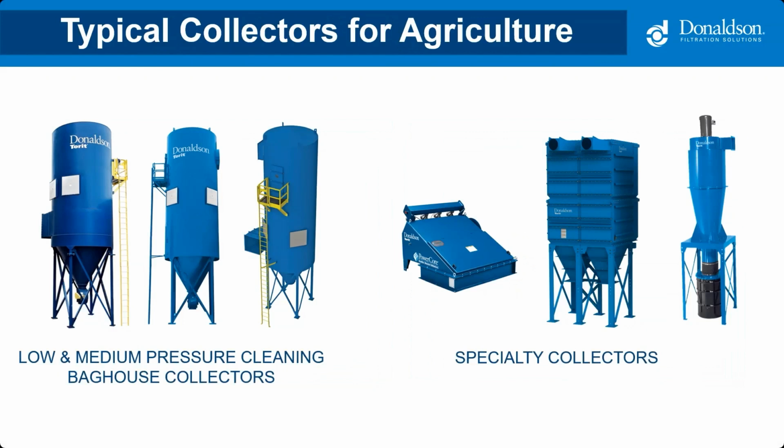So over my career, we've used many different dust collector types on agricultural applications. And when applied appropriately, all of them work. Some can be successful, some aren't. If you put the wrong collector in the wrong application, you can quickly get into trouble. Most commonly used are round bag houses. That's the type shown on the left here. We use that type of collector primarily for heavy agricultural.